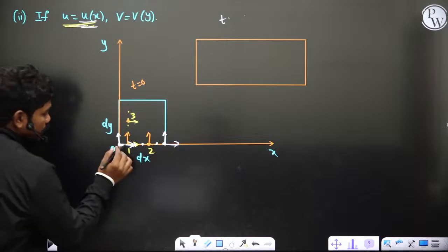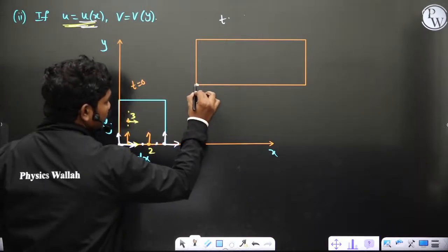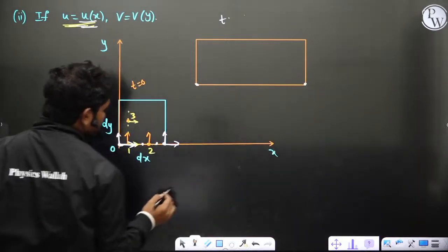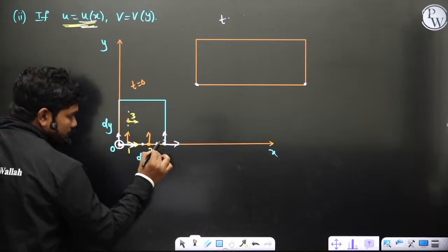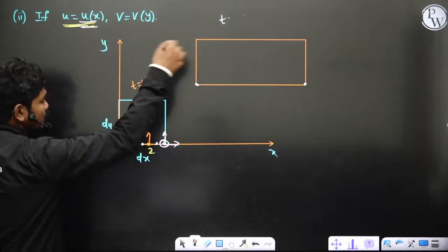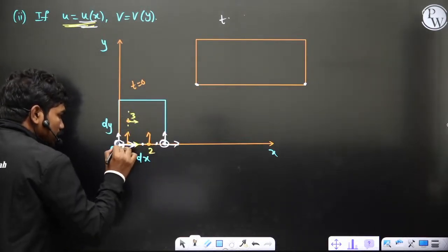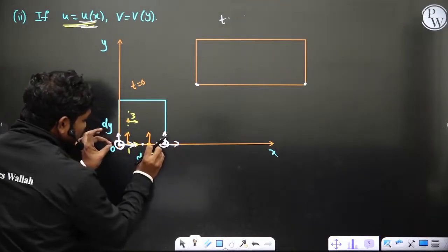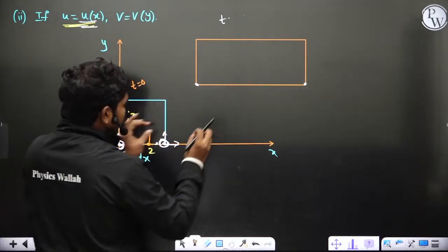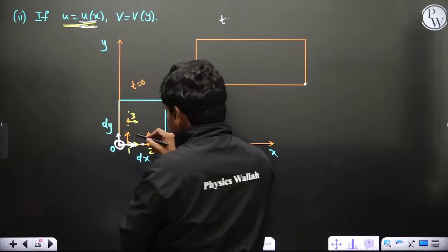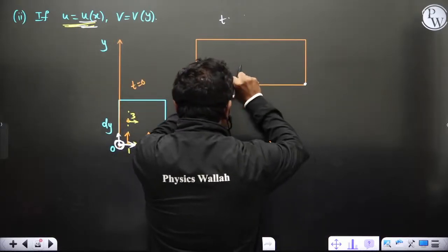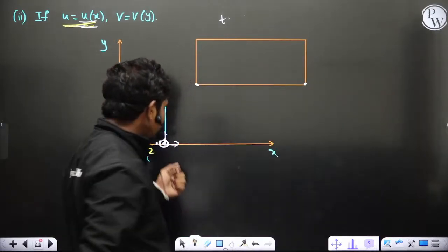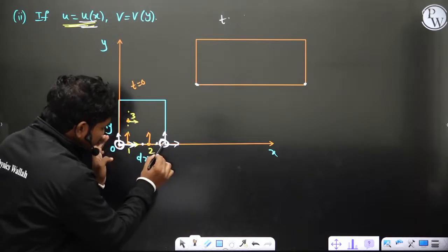That means, let us suppose these 2 particles got shifted to this vertical location, but compared to this particle, this one will move fast, okay? Let us suppose it's an increasing function, then compared to this particle, this one is moving fast. That means whenever this edge is going here, along with getting displaced by this amount because of these vertical velocities, this element will also get stretched in the x direction because this particle is moving faster than this.